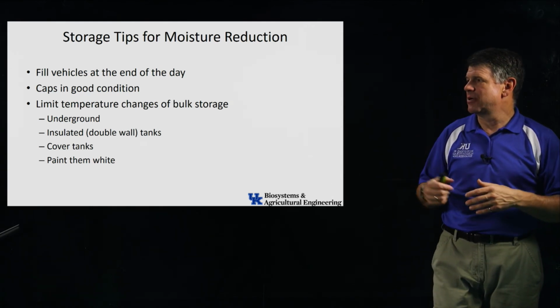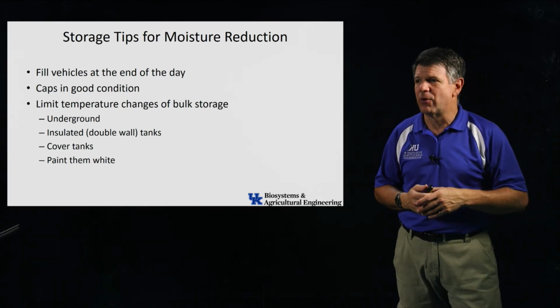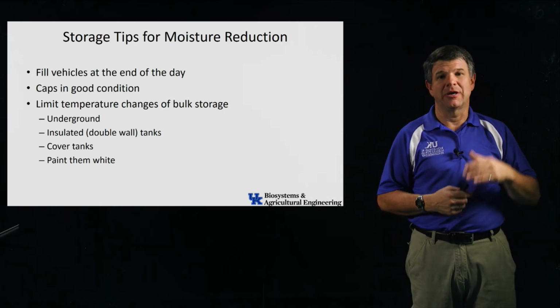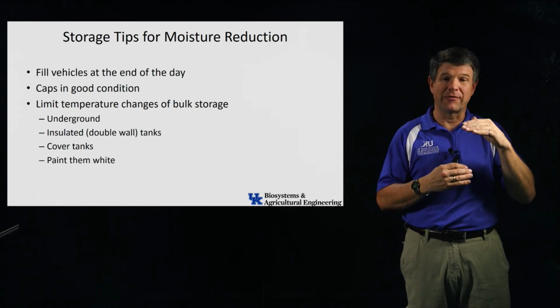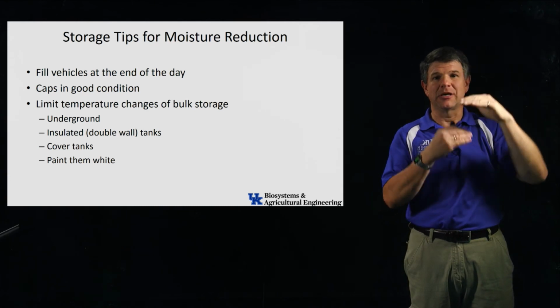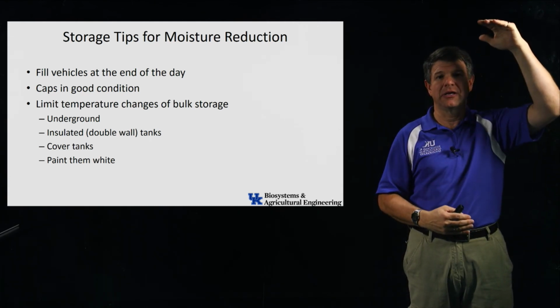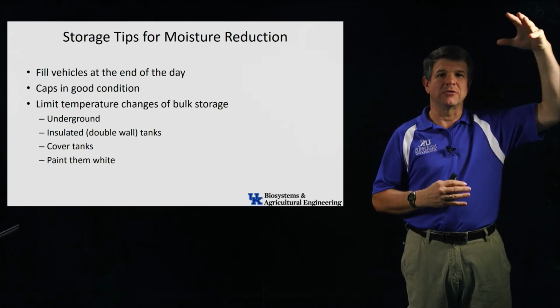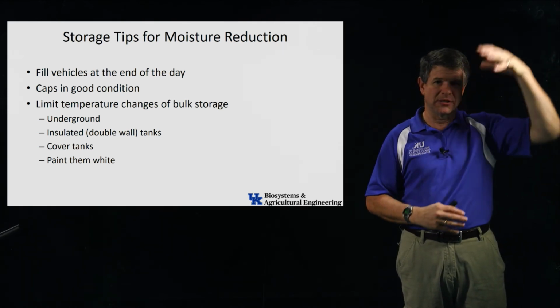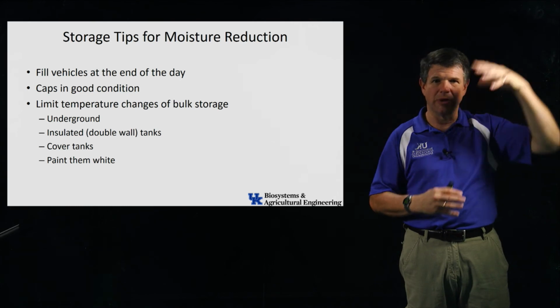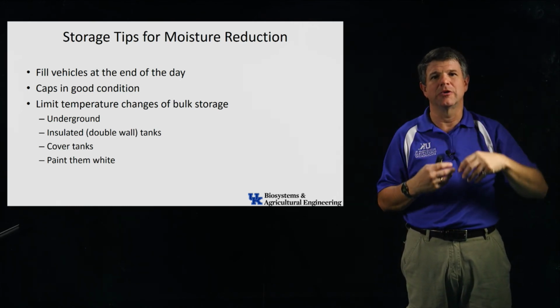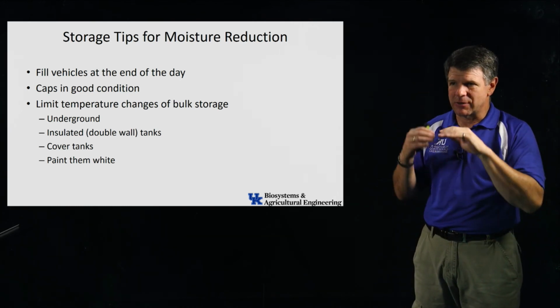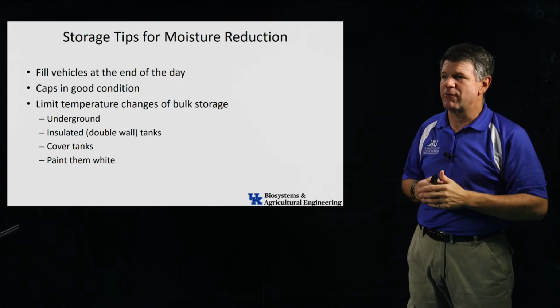So keep the caps in good condition, and if you're going to store your fuel, underground's the best place because the temperature doesn't change. If I've got a tank with headspace in it and it heats up and cools down, say a black tank where the sun hits it in the day, the fuel expands, the air expands, it goes out of the vent, and then at night it sucks that moisture in. So I keep pushing out and pulling in, pushing out, pulling in. I keep pulling more and more moisture in there, and that's a bad deal. So do anything I can to stabilize the temperature of my fuel storage.